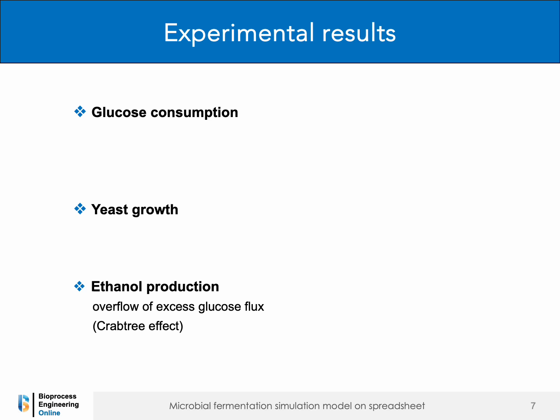The fermenter is continuously aerated and stirred to avoid oxygen limitations. During the fermentation, medium samples are taken at increasing times. They are analyzed for the concentrations in grams per liter of glucose, ethanol, and dry weight yeast biomass. At an initial 50 grams per liter glucose, the yeast growth takes place over a 10 hours period. The glucose concentration decreases first slowly, then more rapidly until complete consumption.